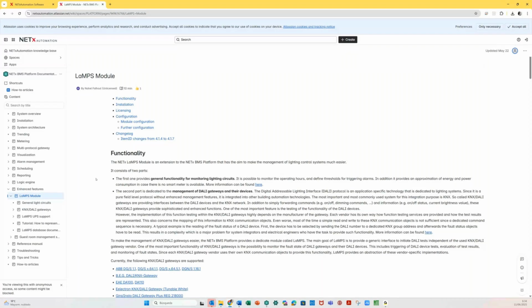There has been an evolution during the last years in DALI technology. The first thing we have recently incorporated in our projects is the new ballast like DT8, for example, where you can change the color temperature. You can also integrate RGBW controls, more sophisticated than before. All these kinds of things are really interesting.